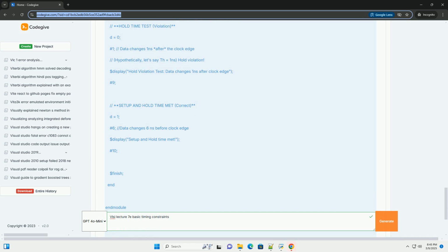The problem: when a signal transitions between two clock domains, the sampling flip-flop in the receiving domain might violate setup/hold times because the arrival time of the data is asynchronous to the receiving clock. This can lead to metastability.